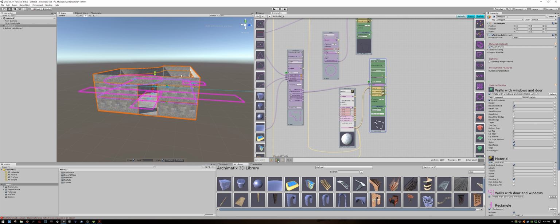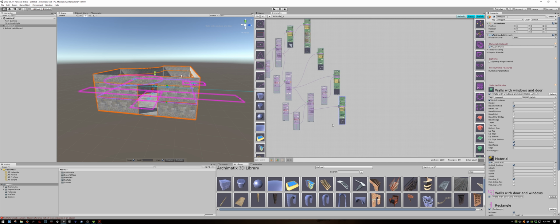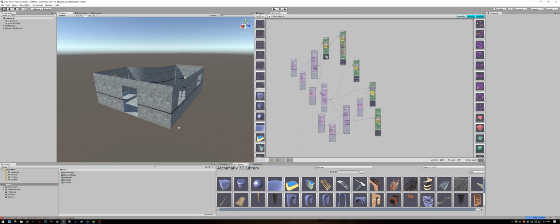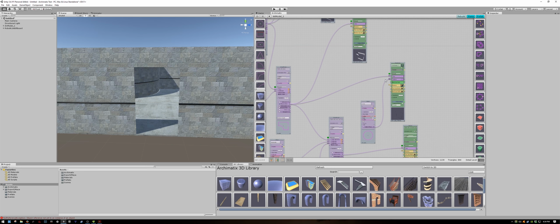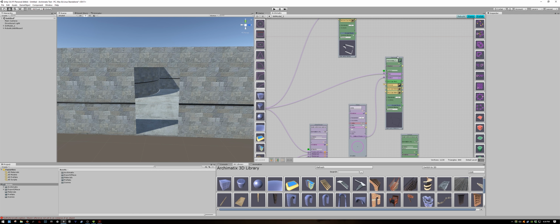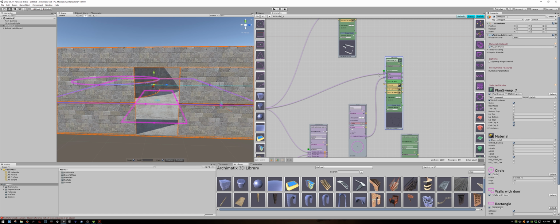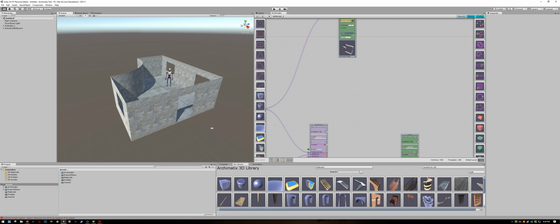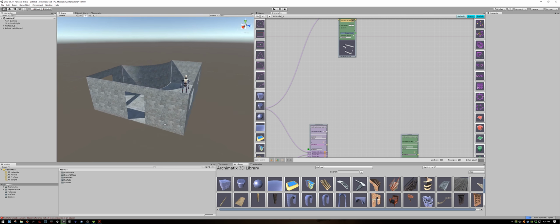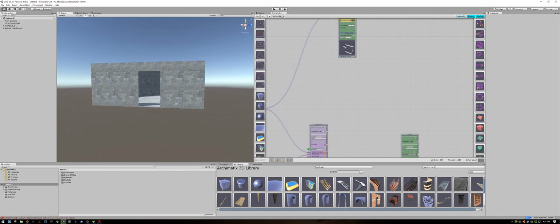Okay, now I'm gonna hide my tools so we don't need to see the material anymore. And if you don't want the railing, we can delete the railing. So where is our railing? This is it. So I'm just gonna delete it. I don't need the shape for it anymore, the cross-section shape. And we basically have a room with doors and windows.